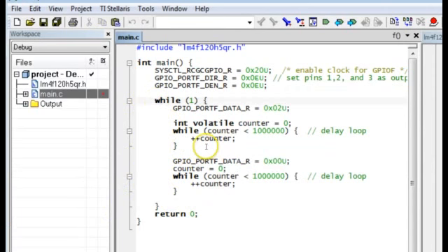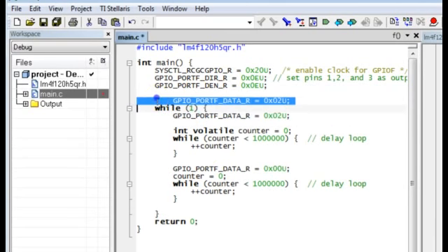In this lesson, your objective is to use the other colors of this composite LED, such as the blue and green colors. Suppose that you want to turn the blue LED on and keep it on all the time while you blink the red component on and off. How do you do that? The first step is simple. You need to turn the GPIO-F data bit 2 corresponding to the blue LED before the endless loop.